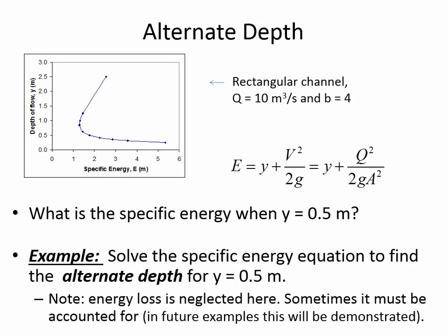All right, so this is basically just assuming that the water has a certain amount of energy, and we want to know the 2 different flow depth possibilities. And the reason why we do this is that this kind of diagram is very, very helpful. Let me just show you a quick preview of the application. Let's say that you have a channel, and the water is flowing. It's uniform flow and it's steady.